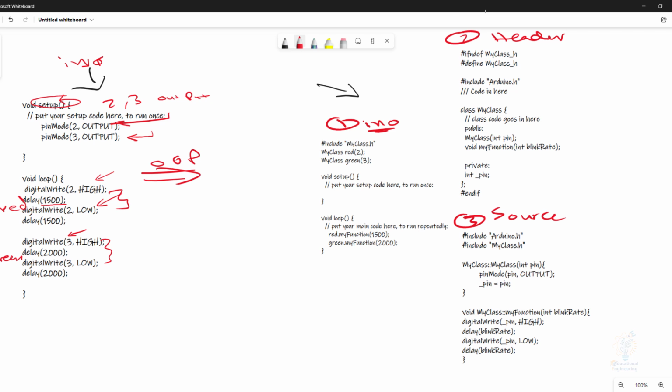Now if you did use Arduino libraries before, then you must be familiar with these terms, the header and the source file. Now, the header file will include the prototypes for functions and for almost everything you want to use, while the source file will include implementation. Now, every Arduino library or every C library must have these two files, a header and source file. Now, this INO file is the project file. We call it a project file here for simplicity.